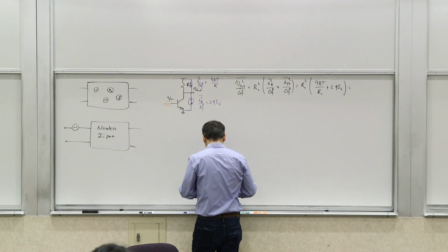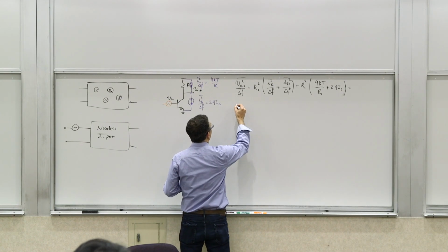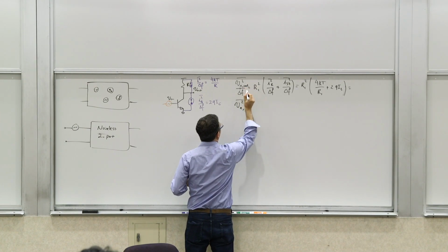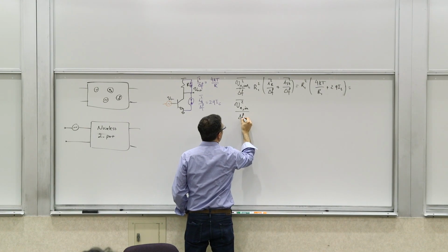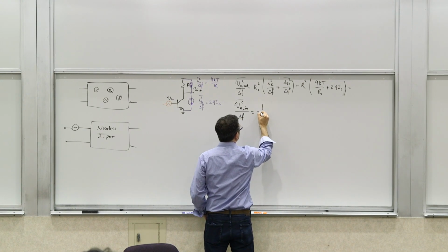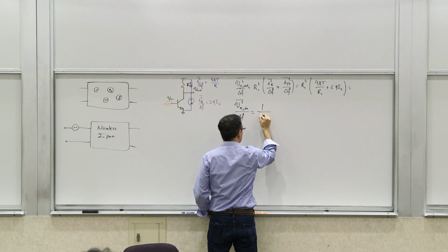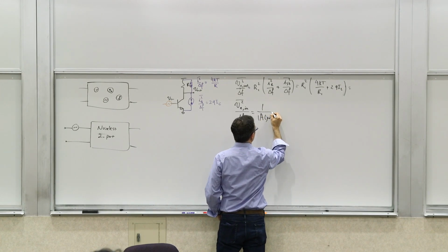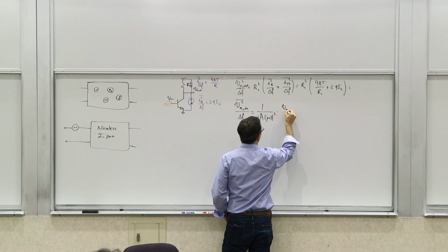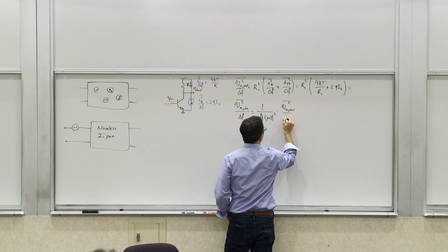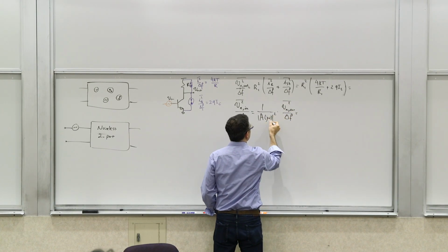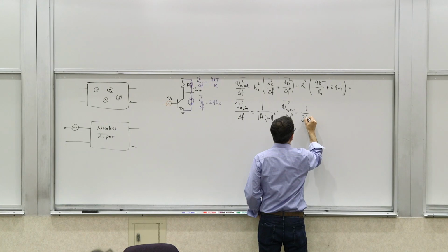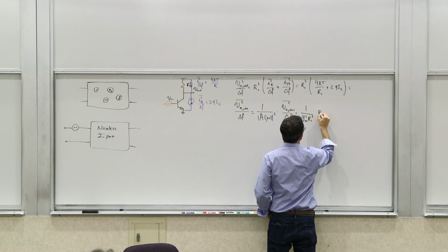So if you take that and say, okay, then Vn input, this would be Vn out, equivalent over delta F is basically 1 over the transfer function magnitude squared. So in this case, it would be 1 over A of j omega magnitude squared times Vn out squared over delta F. And now, of course, this is simply gm R1, because right now we are looking at low frequency, so it becomes 1 over gm squared R1 squared times R1 squared.